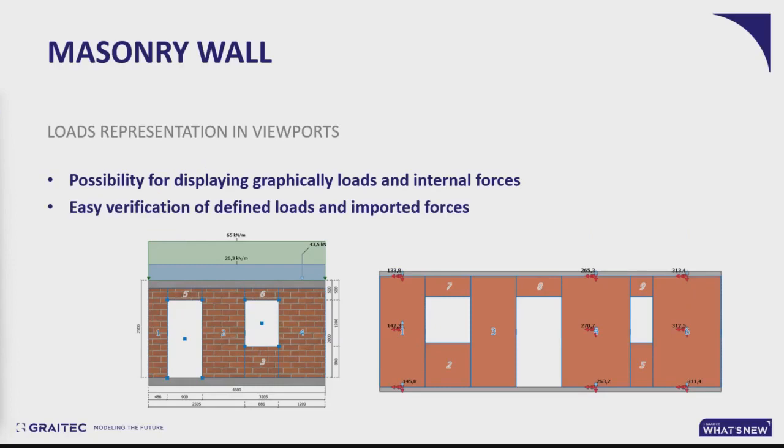And we can also display now resultant internal forces from vertical design sections, as on the right picture. There are even separate and dedicated diagrams for such integrated forces. Now you can see easily such design values on top, in the middle, and at the bottom of each calculation panel.